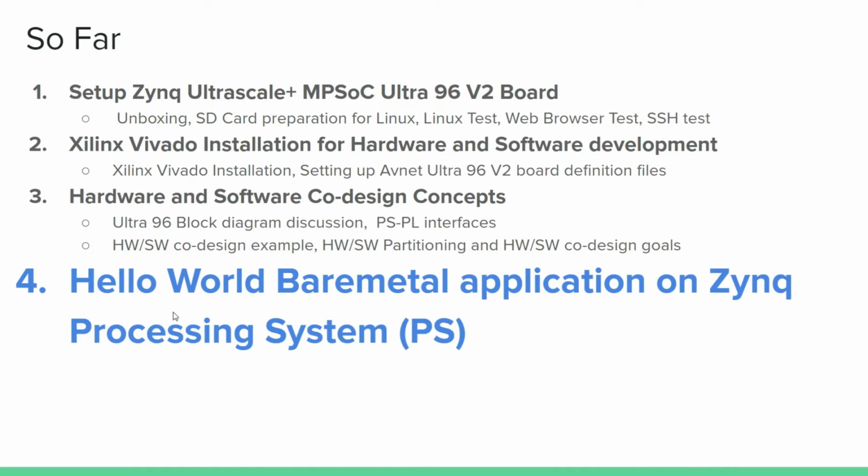So in this video, we are going to be running our first Hello World application on the Zynq processing system. And as I said in the hardware software co-design concepts, when we say Zynq processing system, that means we are running our application on the processor cores, in this case on ARM cores.